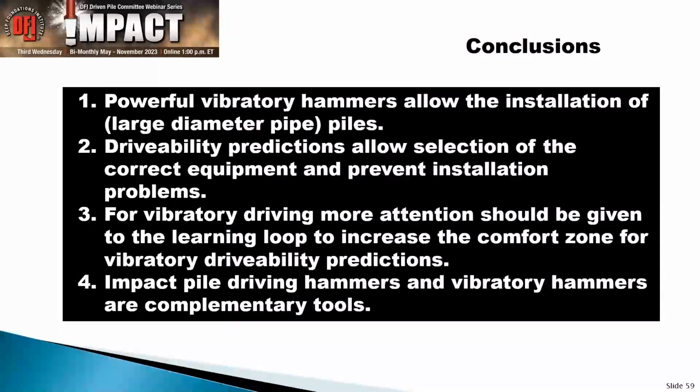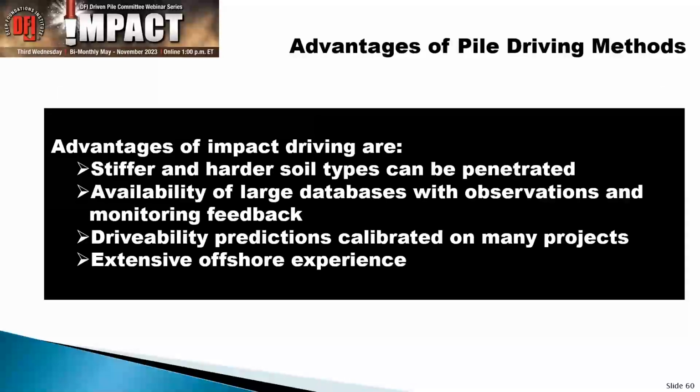Finally, because I don't want people to get the wrong idea, I'm not saying that we should drop every single impact hammer and only use vibratory hammers. They're complementary tools, and every method has its pros and cons. When you talk about pile driving with an impact hammer, there are stiffer and harder soils that you can penetrate with an impact hammer that you cannot go through with a vibratory hammer.